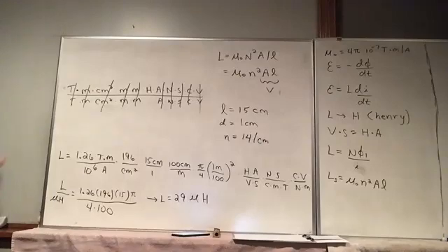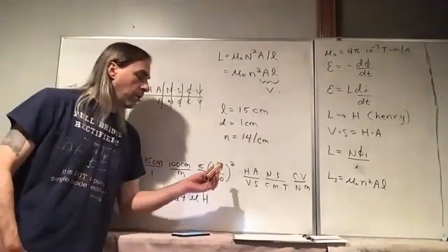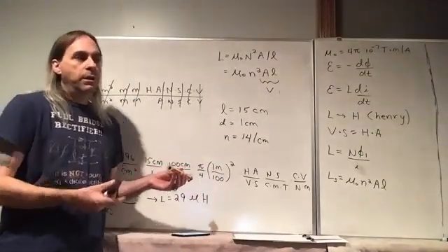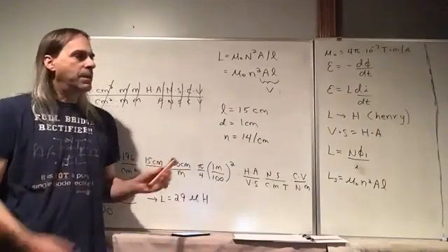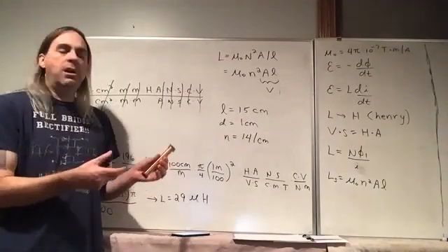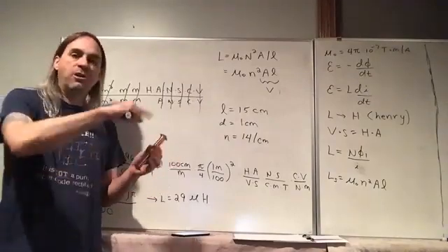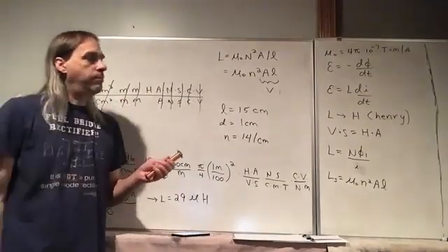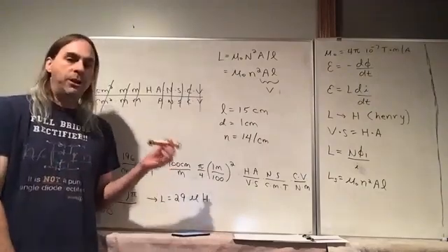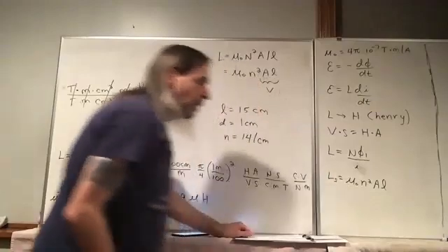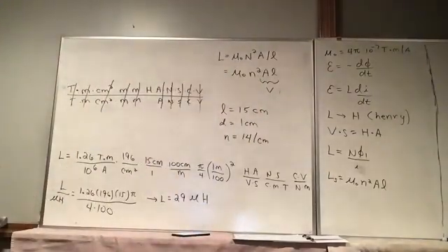You can think of inductance as a kind of inertia for a circuit. So if you have a circuit with a solenoid in it, you flip a switch, you're building up a current. This is going to fight that. It wants to keep that current from happening. So the current will build up more slowly. Alternatively, if you open the switch in a way where you still have a full loop, the current wants to drop to zero now, but this is going to prevent it from immediately dropping. It wants to prevent any change in the current.